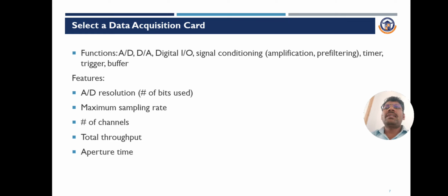So it is possible and desirable to describe the operation of a measuring instrument or system in a generalized manner, without resorting to the details of the physical aspects of the system. The whole operation can be described in terms of functional elements. Most measurement systems contain three main functional elements: a primary sensing element, a variable conversion element, and a data presentation element. Each functional element is made up of distinct components or groups of components, which perform the required and definite steps in the measurement.